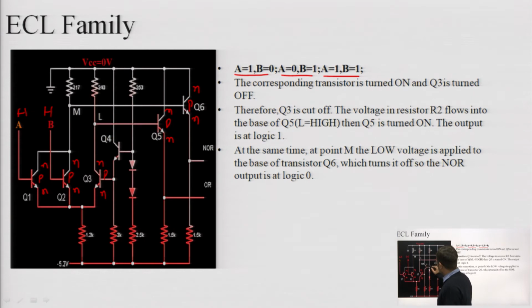It is a part of a compensation network, so we are not marking anything on this one. So we will not be interested in the conduction of this transistor. So Q1, Q2, Q3, Q5 and Q6. These 6 transistors will decide the on and off states of this particular gate.